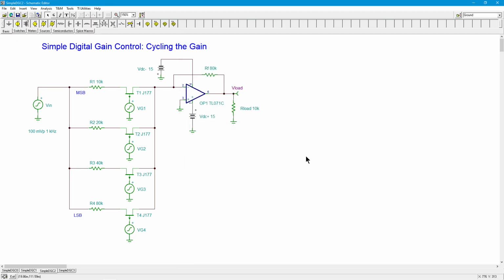Well, in some applications, it's not really going to make much difference. If you're going to cycle through things very quickly, and if this was like an audio kind of thing, you're going to hear these ticks and pops going through. That's not too cool. You basically have a couple of ways of doing it. You can slow down the edges on these sources through a little RC network. You make a little lag network, all right? So, like maybe a couple K ohms here, and then you got like 10 nanofarads or something like that.